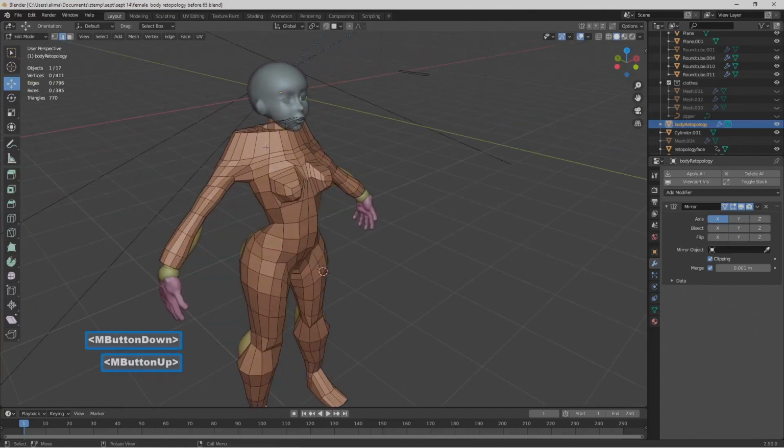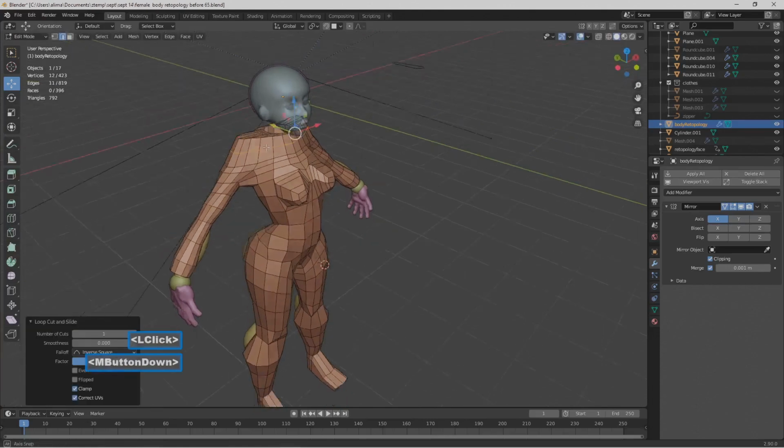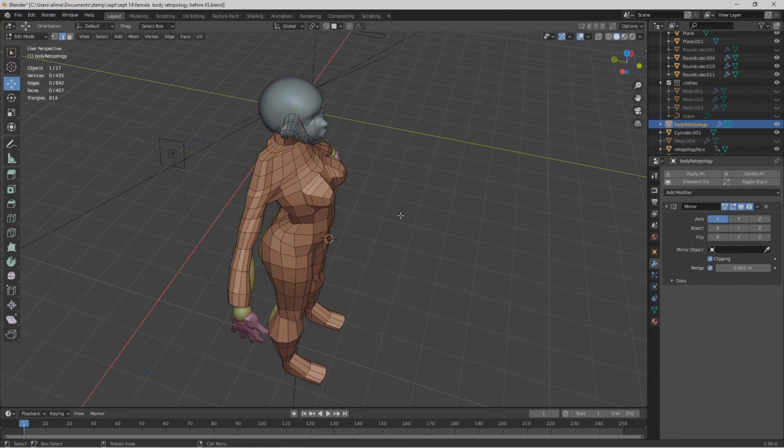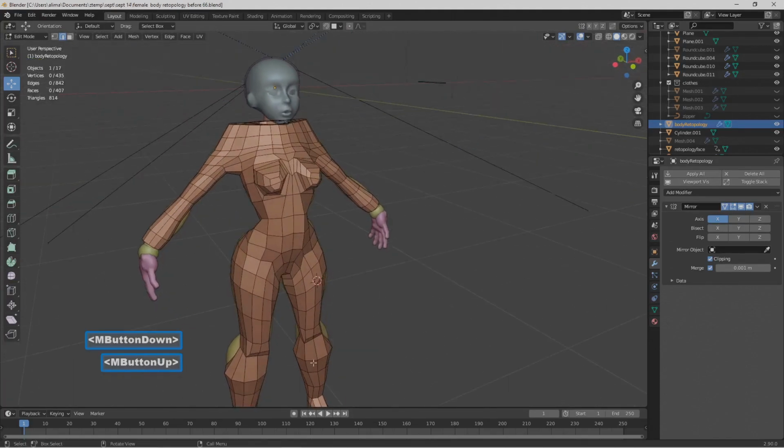Okay, I'm holding the middle mouse button. I'm going to hover here, hold control, press R. Left click once, left click a second time to put that loop cut in. I'll hover here, hold control, press R. Slightly difficult to see. I'll left click once, left click a second time, so I put in geometry there. I'll left click on nothingness to deselect. Okay, I put in that extra geometry as far as those edge loops so that when we put our shrink wrap modifier, I'm holding the middle mouse button, rotate to deal with this as well as this. It'll go better to the body.